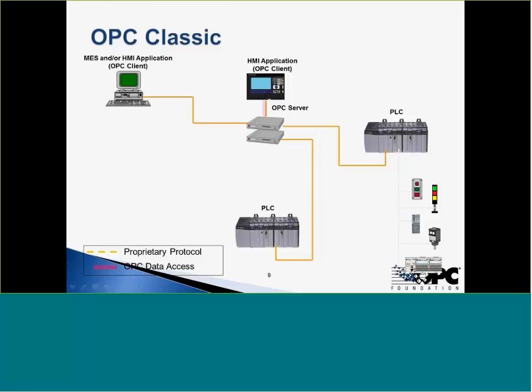And if you could see this properly, what you would see is that the server is either receiving messages from the underlying devices or it's actually polling the underlying devices, but the client application never knows and never has to worry about the intricate details of communicating with the underlying devices. All it has to do is say, server, please tell me I want this tag, and I want this tag at this particular rate only when it changes.